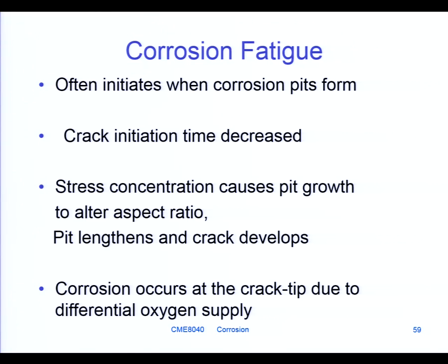And the pit, when it initially grows and there's no stress effect on it, will grow hemispherically. That's not quite a hemisphere, is it? Let's try that again. That's better. And then once it begins to notice the environment around it, there's a possibility for it to start to change in aspect ratio and elongate in response to the stress, which again is at right angles, and eventually to form a crack.